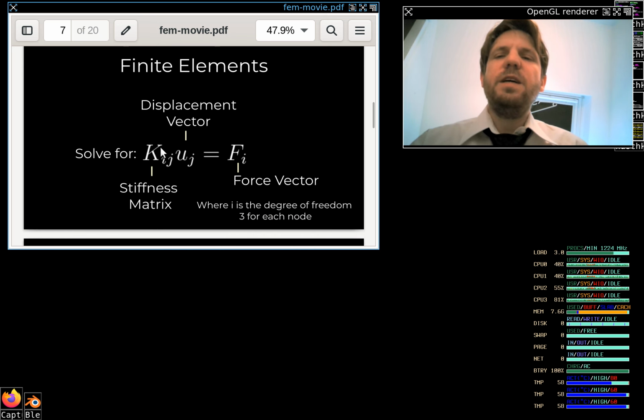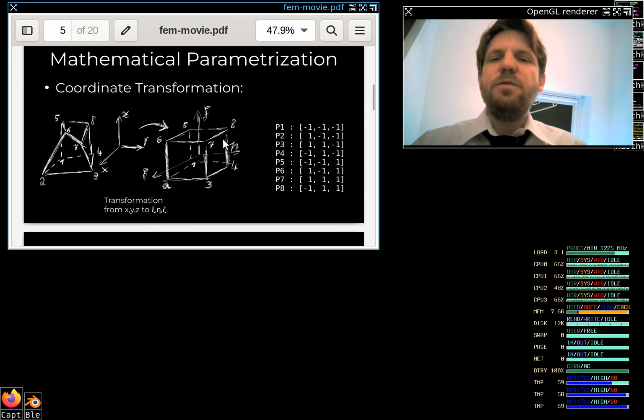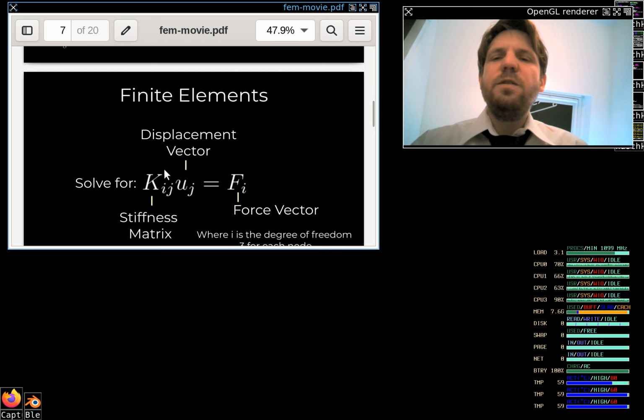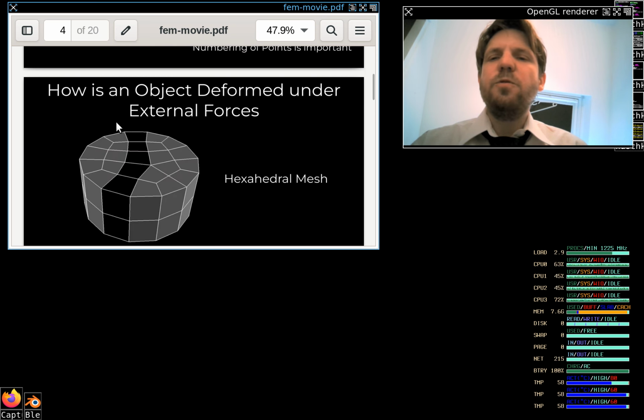So we do this element wise, and the basic idea is that you do this for each element and sum it at the right point. So for ij, where you have the coordinates here, into the global stiffness matrix from a more global mesh.